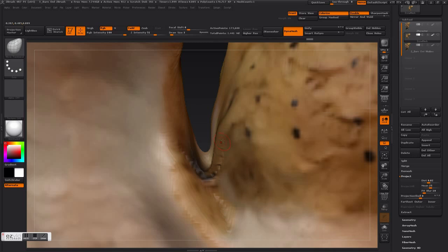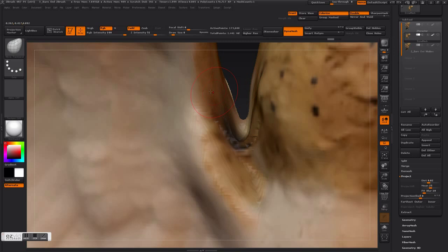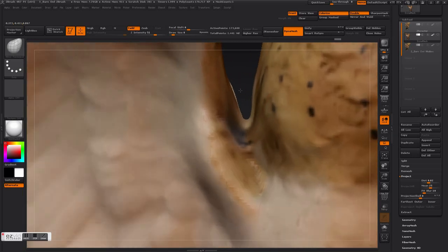And there it looks like there's a big vein which is going out, but I think that's just part of what I've done. So if I just pull that in, smooth that out. Now you can see I'm smoothing the texture as well as the geometry. Now sometimes you'd want both, but this time around I think if I just turn off RGB, then it should. Actually, it doesn't seem to be working this time. Oh, I know why. Each time you press a button, Control, Shift, etc., they've got different tools on. So if you hold down Shift, you see the RGB still on. So you just click that away, and now it works.